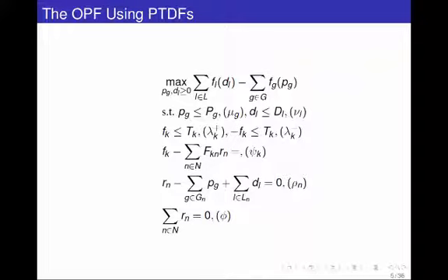The interpretation of a dual variable in terms of sensitivity is that if you increase my right-hand side a bit, the lambda captures the increase in the objective function. So if it's positive, what can you say about a line? Would it be possible for a line to not be congested, which means that the flow is equal to the max limit over the line, and have the lambda positive? If the f on that line was strictly below the limit of the line, would anything change?